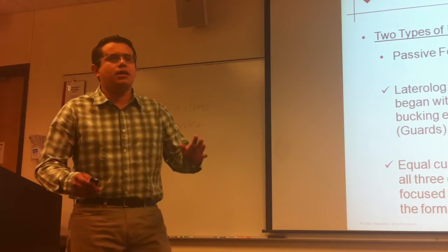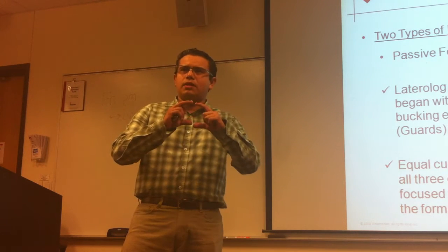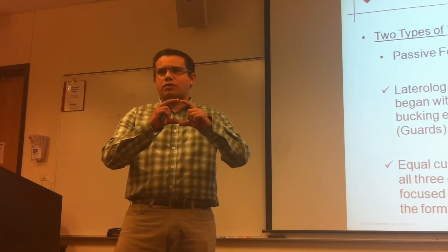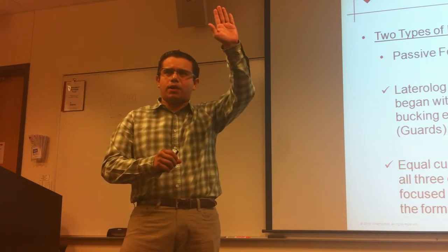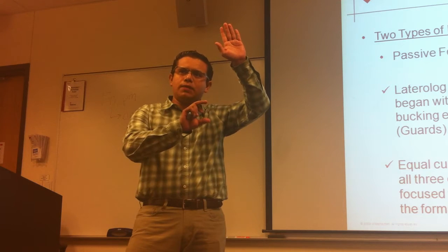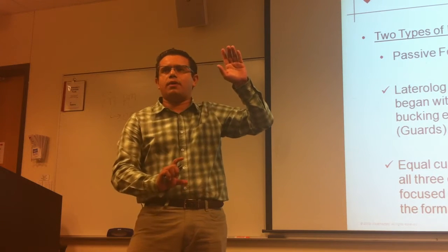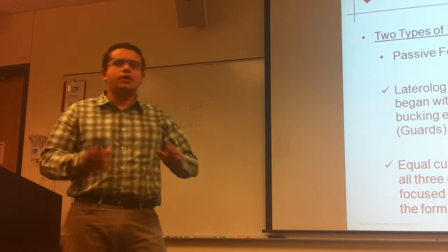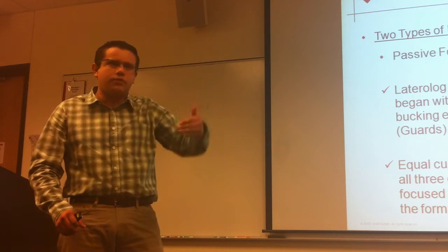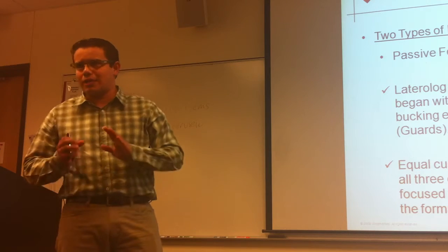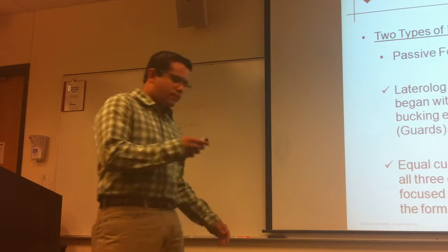What they did is that before, we had a current emitting electrode, and they added 2 more electrodes to back up that current. So we have one upper bucking electrode, the measure emitting electrode, and a lower bucking electrode. We are trying to push the same amount of current on the 3 of them to make sure that the current goes laterally and deep into the formation.